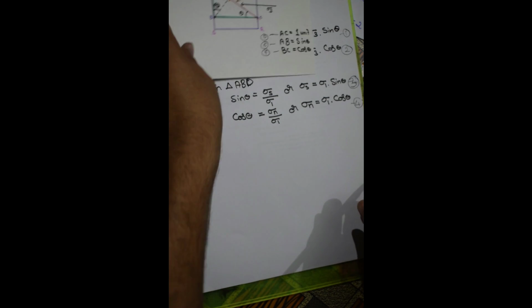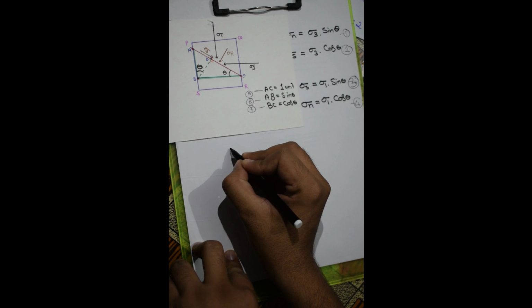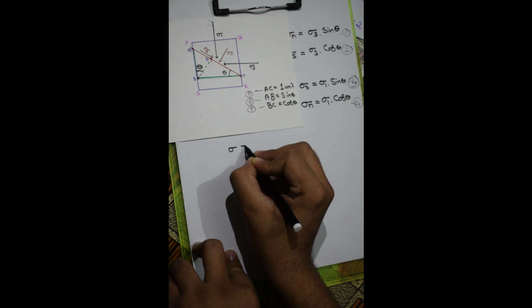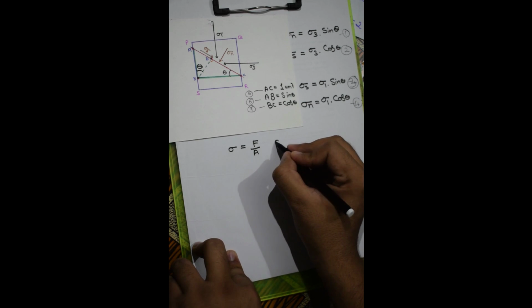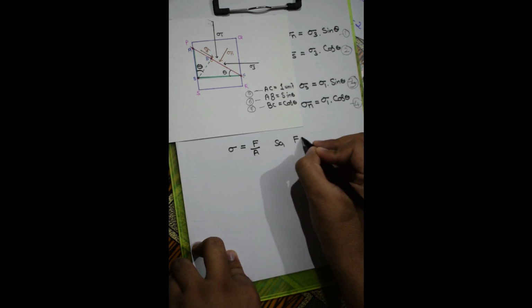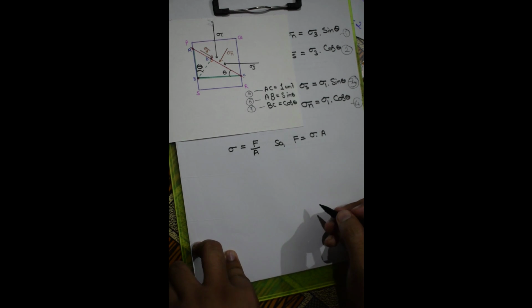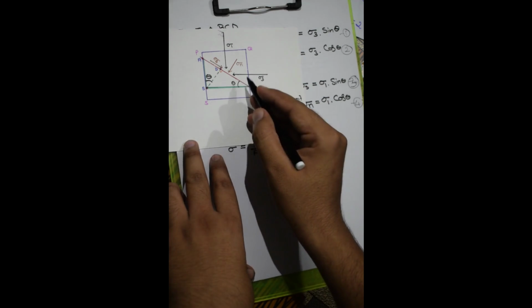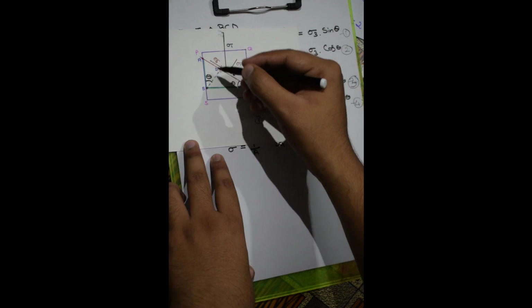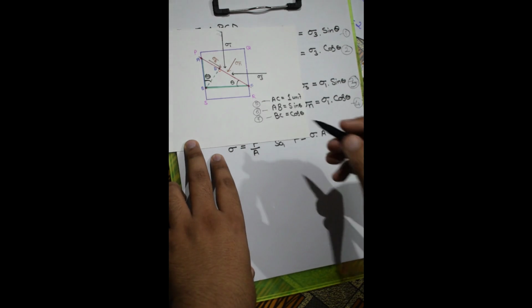Okay, now we all know that stress is equal to force per unit area, so we can rewrite the force as stress multiplied by area. Now if you take a look at this triangle here, and how these different stresses are oriented along a point in this plane AC.